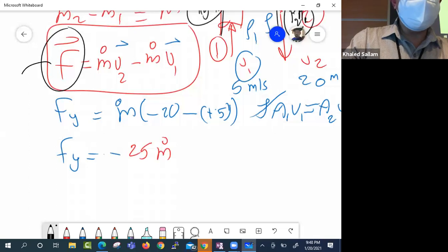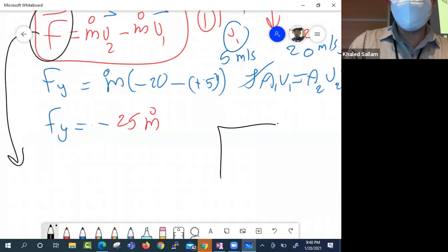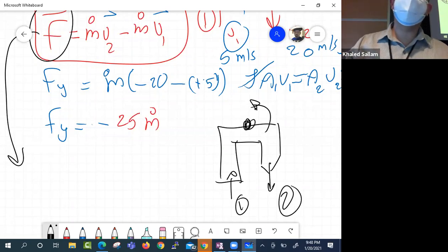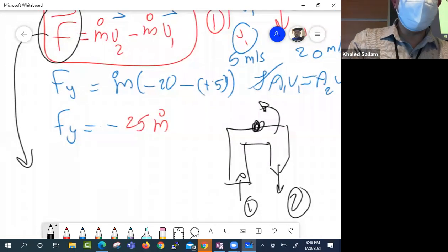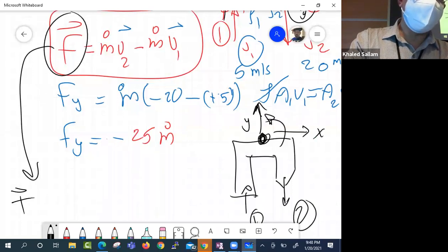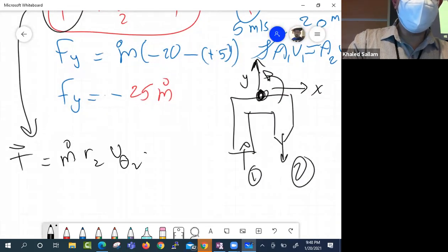But the point is that with that equation, if you take the moment of that equation to calculate how much torque is actually being applied, say you are holding it here and you are worried that it will end up twisting the weld because of the angular momentum it's exerting, then, with this as the x-axis and this as the y-axis anchored from here, the equation becomes torque equals m dot times r2 v theta 2 minus r1 v theta 1.